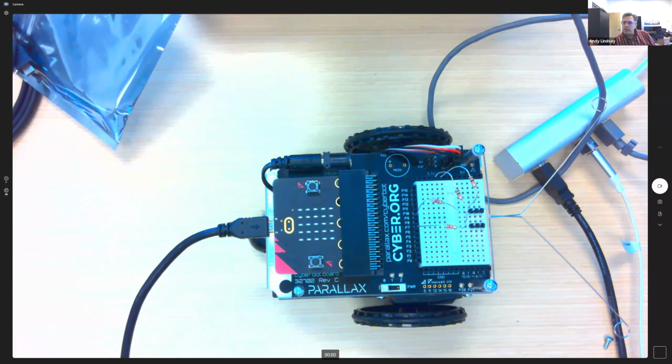Okay, if it's going in a circle, then does that mean one wheel is faster than the other? Yes, possibly. Let me think about this. It should just turn in place if it's going in a circle by turning in place. It might mean that it thinks that one whisker is constantly pressed. If it's kind of curving in a large circle, yeah, that's where you'd go back into the script and adjust your forward speed to slow down the faster wheel.